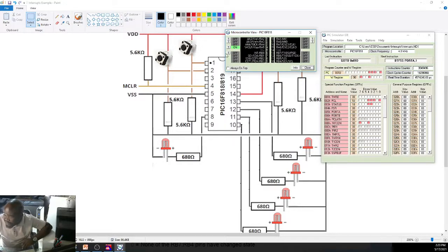Now, what you need to be aware of now is with 2 input zeros, our B2 is also 0, because that's an exclusive OR gate. If I do this, if any of the inputs becomes 1, B2 becomes 1. If they both become 1, B2 is 0.